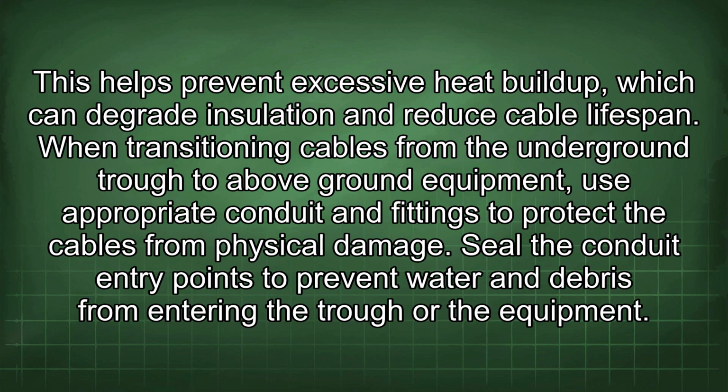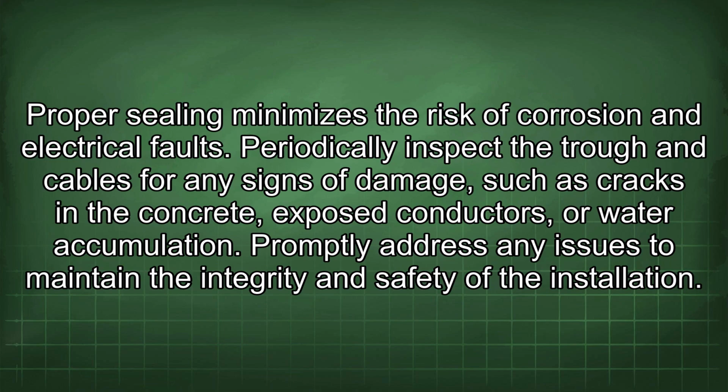When transitioning cables from the underground trough to above-ground equipment, use appropriate conduit and fittings to protect the cables from physical damage. Seal the conduit entry points to prevent water and debris from entering the trough or the equipment. Proper sealing minimizes the risk of corrosion and electrical faults.